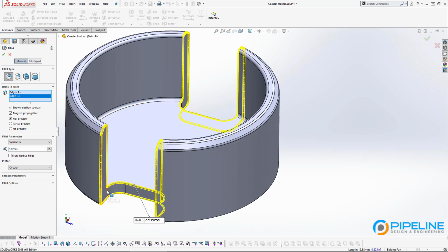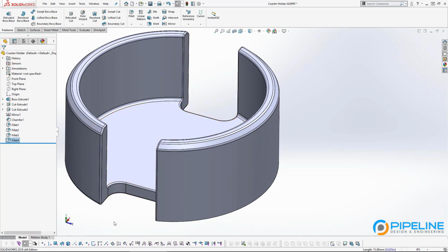Most cases you want to have your fillets look real nice and smooth and continuous, so you'll just do this. If you didn't want to, you could turn that off, but that often creates some geometries that don't work, so you'll see the preview here completely doesn't show any fillet because it wouldn't be able to do this. So I'll reselect that and hit accept.